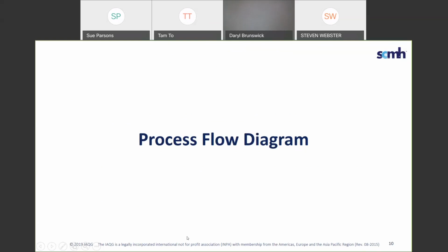So moving on, why is the process flow so important and why do we have it in PPAP? Variation is inherent in every process. A key portion of APQP is the management of that process variation. So as we're trying to minimize the variation, we want to thoroughly understand where it comes from within the process. A comprehensive process flow diagram can help you get there and help you locate where those sources of variation are.